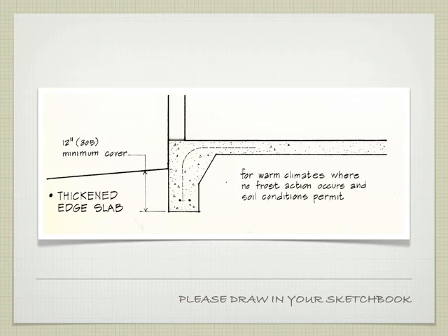So in this particular example, we start with our slab. It looks something like this. When we get to the corner or the edge of the slab, the slab is going to turn down and have a little bit of a built-in footing, something that looks like that, which allows us to have the outside dirt and what would be underneath the slab itself. We'll put a little break line in there. On top of this slab on the corner would be your wall.